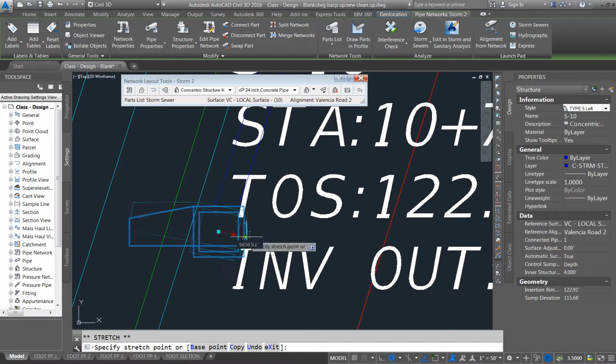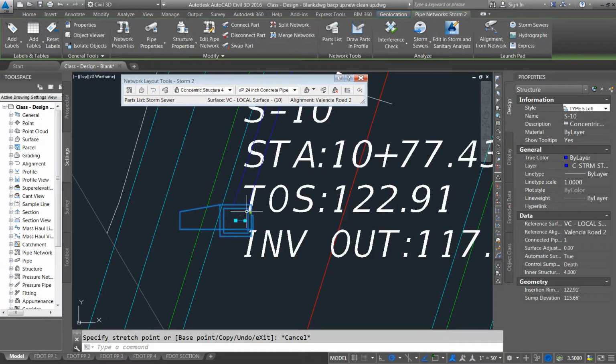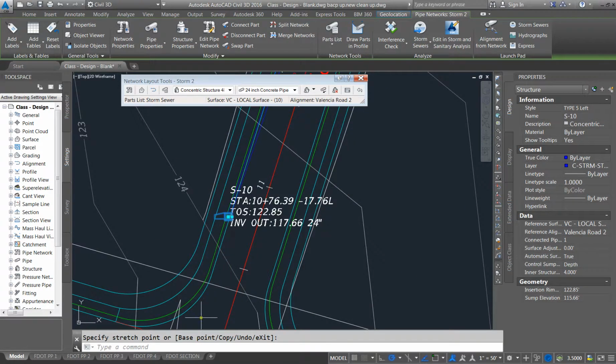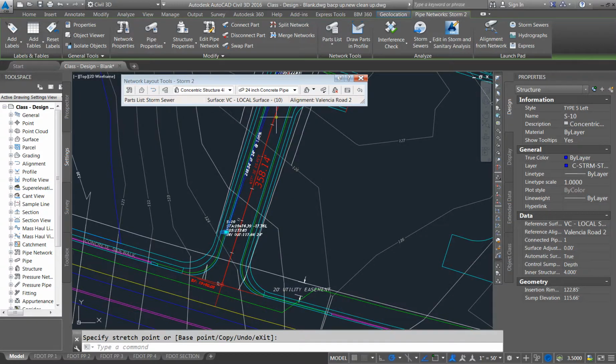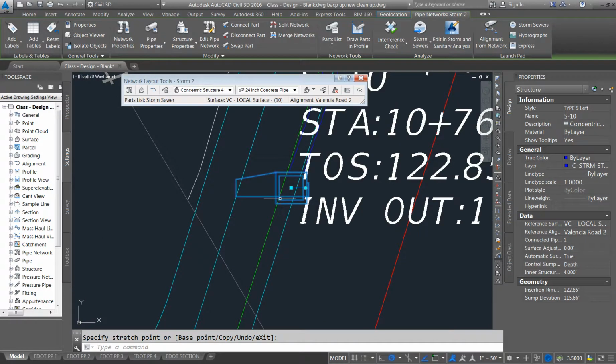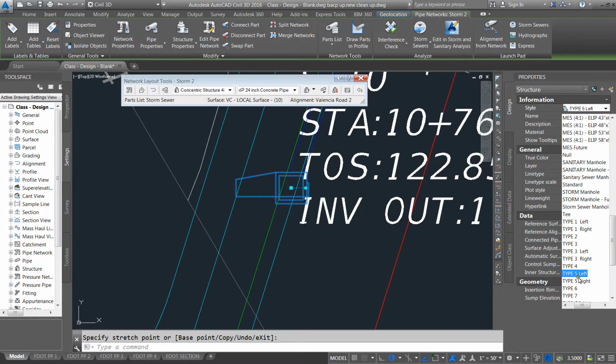When you're doing the location, you can't leave the inlet way out here in the middle of the road. You're going to have to move it over. And if the water's flowing from this point up here down toward the intersection here, this is the wrong inlet to use. You're going to have to change it, so I'm going to go right.